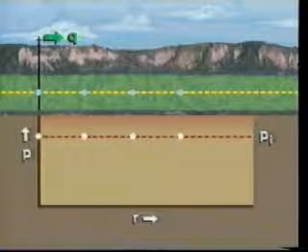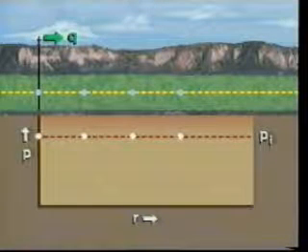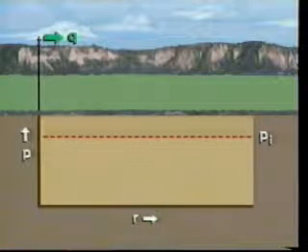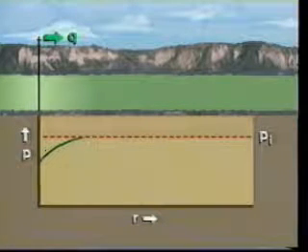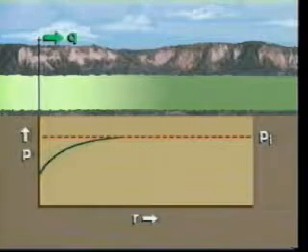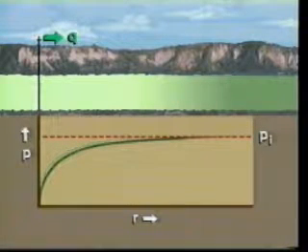As the reservoir adjusts to the disturbance, we measure the response and compare it to an expected response predicted by a mathematical model of the reservoir's behavior. The most convenient way to disturb a reservoir in a controlled manner is by suddenly producing or suddenly shutting in a well. The reservoir's response to this disturbance, a fluctuation in pressure, is easily measurable as a function of time, most commonly at the point of disturbance. The analysis of this pressure data, referred to as pressure transient analysis, can greatly expand our knowledge of the reservoir, as seen through the wellbore window.